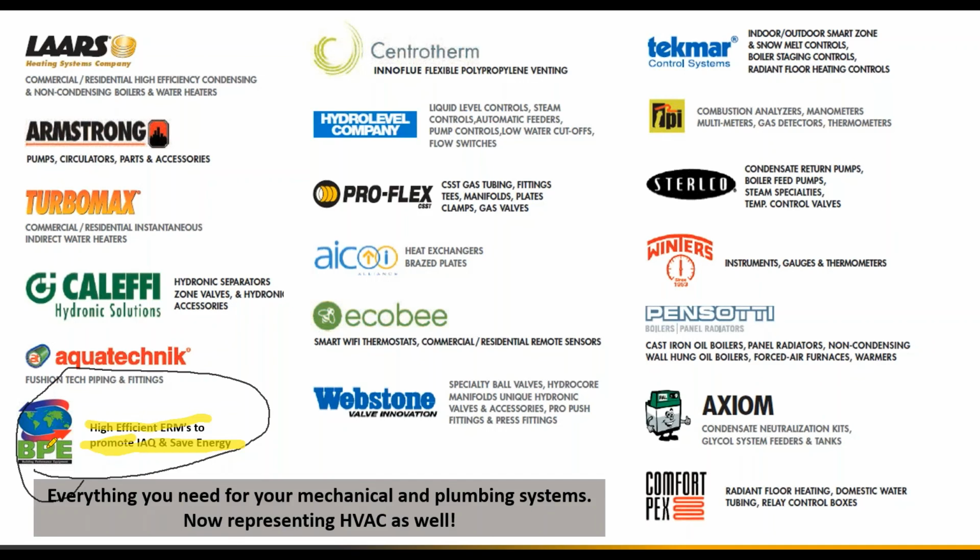The entire system is operating off a single pump, and an outdoor reset. So in the wintertime, for bedrooms that are not in use, we basically have the panel radiator on a snowflake setting. It allows some flow if a room were to get very cold, but for other rooms that are in use, you set what your comfort level is, and it really puts the entire heating system on cruise control.